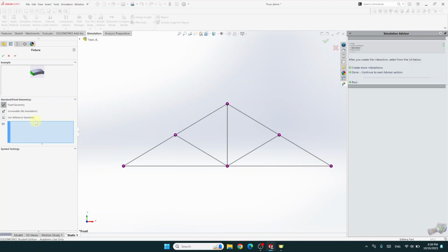So there, because it's not fixed, remember the points to the left, it's a pin connection. We consider that on the left, it's a pin connection. On the right is a normal connection. And everywhere there, we will consider that it's free to slide inside the plane, inside the front plane, but cannot get outside the plane. So our truss doesn't get out of the page.